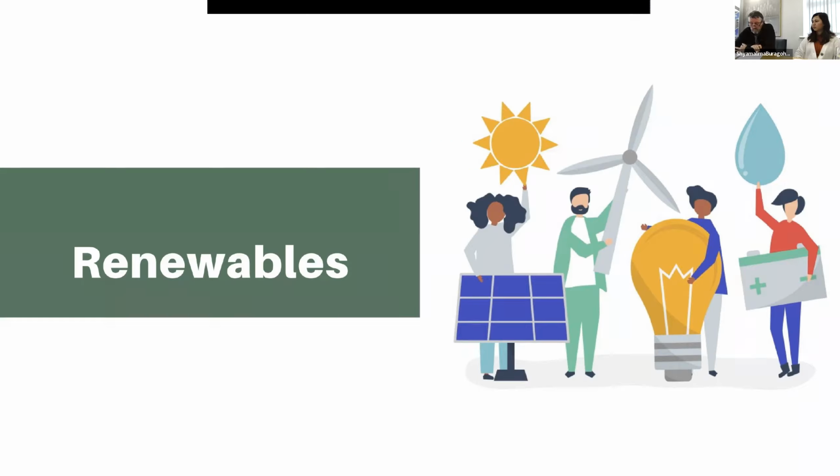Solar thermal is another form of renewable energy that seems to have fallen out of favor. There's a large dedicated hot water volume required for solar thermal units. You really have to have a high hot water demand to make it stack up and to make it worth your while. And the solar thermal units have been found to require a lot of maintenance and a lot of replacement. They were very popular at one stage. They do generate a lot of hot water. You have to have a use for that hot water to justify it, but they were being replaced frequently, which started to eat away at the financial benefits of it.